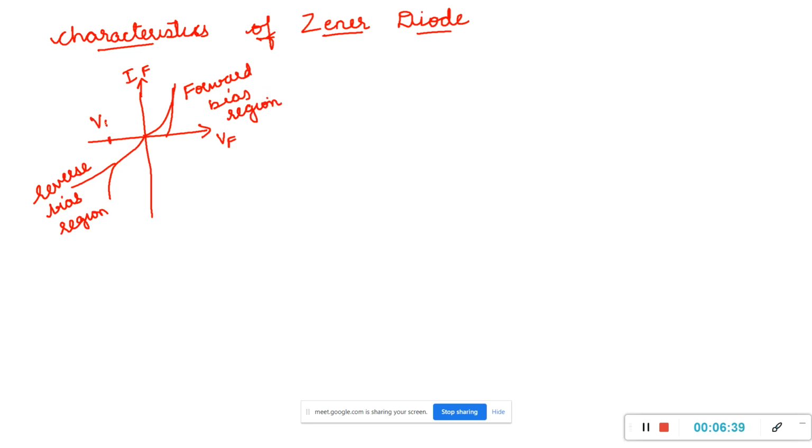So here we have a breakdown voltage VBR, it stands for breakdown voltage, and cut-in voltage is 0.7 volts. After the 0.7 volt the current starts increasing exponentially. So here you can see the characteristics of normal diode, operating regions, and the characteristics of the normal diode. So here this portion we can see the shaded area, and this portion we can see forward and the reverse. This is the characteristics of the normal diode.